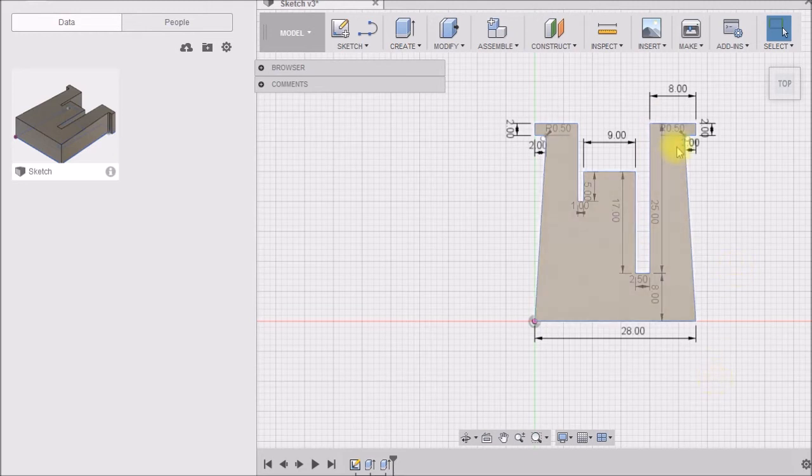When I tried to then taper the sides of the part, as I did in my third and final version, I ran into an issue with Fusion sketches. They have what they call constraints that are added when you draw your lines, and that ties in also to the built-in snap grid, where they snap their points to coordinates that are on that grid.